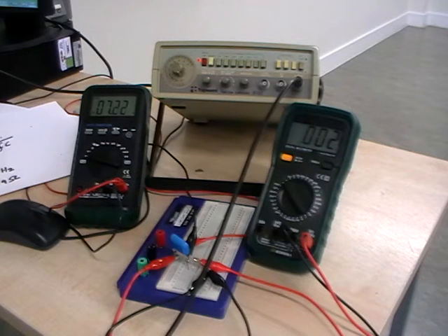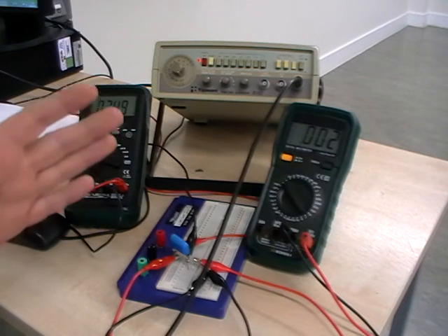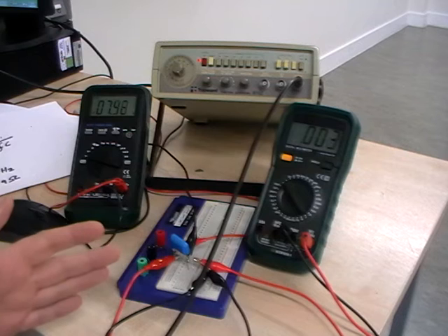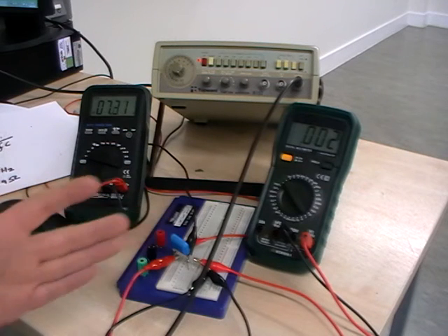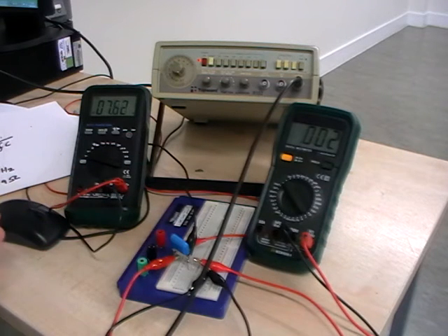We could sit down and do the exact calculations. But again, this is just about showing you a principle. And the principle is that as we increase the frequency, the reactance or the resistance will go down with our capacitor, the apparent resistance. And again, we know our resistor doesn't change. It's going to be 150 ohms all the time. Doesn't matter what signal we are feeding through it.